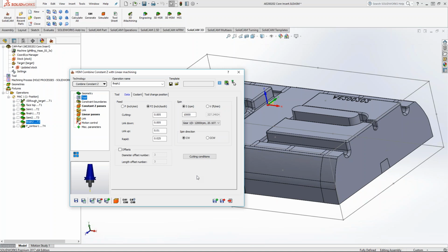2/10 on those inserts normally have like a 2 to 3/10 hone edge. So it wasn't actually getting the cut underneath or the hone edge. So it was basically just rubbing. That's just something I stumbled across, really.